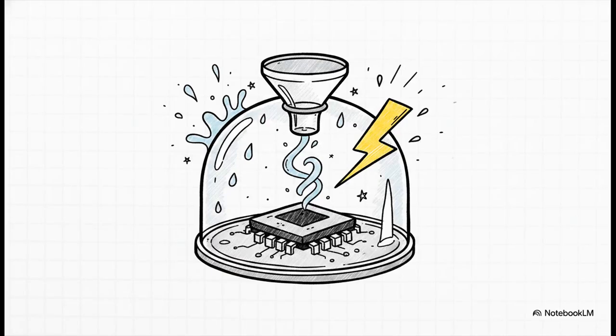So the crucial point here is what we call the packaging problem. If you build a standard computer chip, you seal it tight in plastic to keep the environment out, right? But a MEMS device or nanosensor is designed specifically to sense the environment. A pressure sensor needs to physically feel pressure. A gas sensor needs to touch the gas. Therefore, unlike standard semiconductor packages, MEMS packages must provide mechanical support and a fluid or optical interface, all while somehow keeping moisture, dust, and corrosive contaminants out.